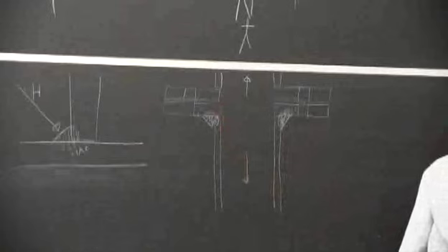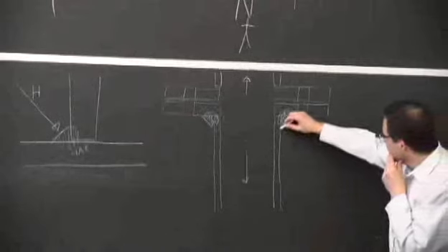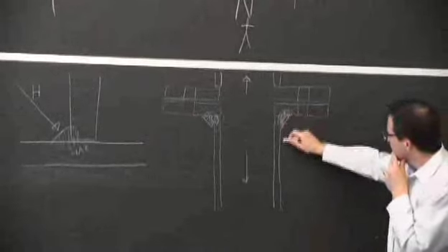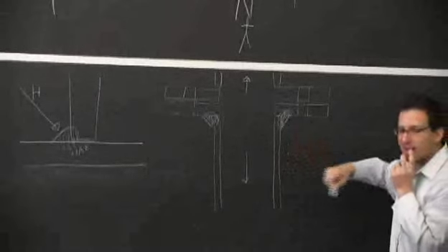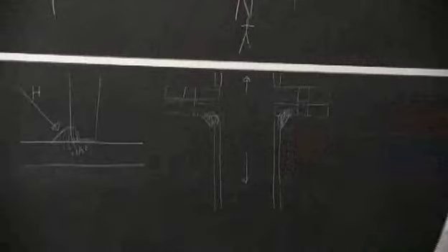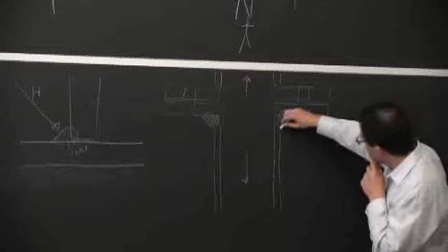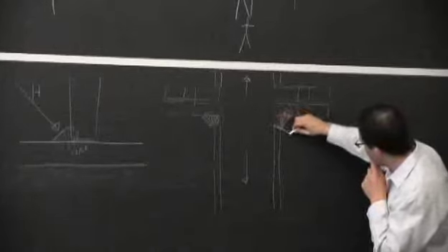Where do you think it's going to crack? At the edge of that weld. Yep. With the weld, see, I did the weld bigger than the thickness of this pipe. It's not that hard to do normally, but it doesn't help too much because what becomes your weak path is right here through the toe.